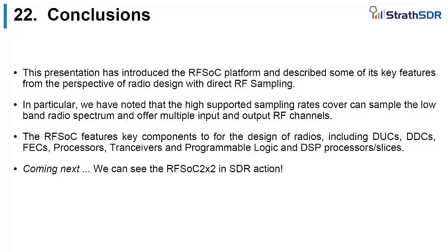So, a few conclusions. What have we done in this presentation? Well, we have introduced the RFSOC platform and described some of the key features from a perspective of radio design and direct RF sampling. We've also noted the high value supported sampling rates we can cover, so up to, again, a few gigahertz, and some of the radio standards that we can therefore directly digitize. We've looked at some of the basic features. We haven't described them yet, but digital up converters, down converters, forward error correctors, some of the processors, and all of these will come together to build our software-defined radio.